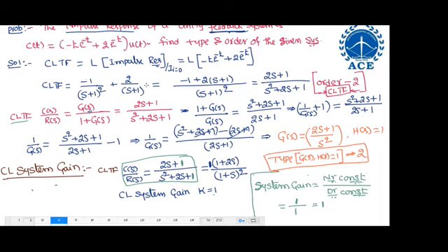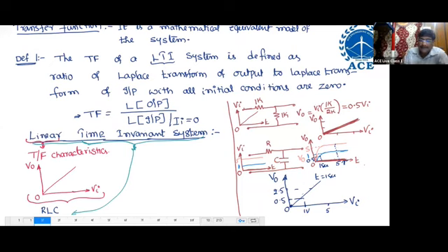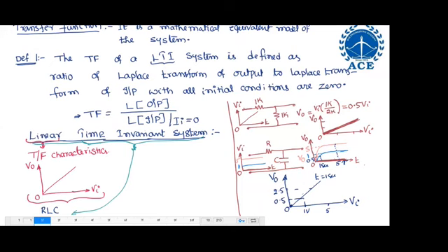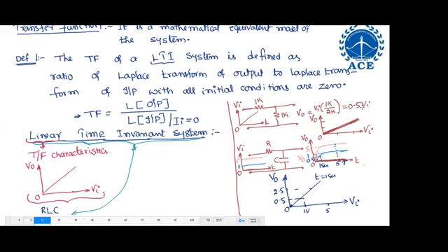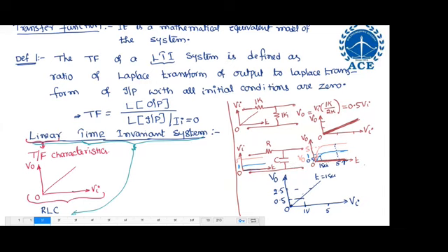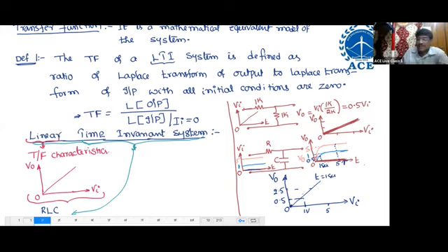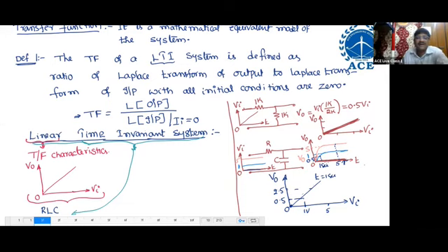Okay, sir, page 1F. So, how did we get the transfer characteristics of that RC network? Find output by input. 0.5 Vi, right? Sir, RC network: input 0 means what is the output? 0. Input 1 means what is the output? Exponential rise to 1. So the capacitor charges. How will the capacitor charge? It is simply the charging curve of the capacitor only, right?